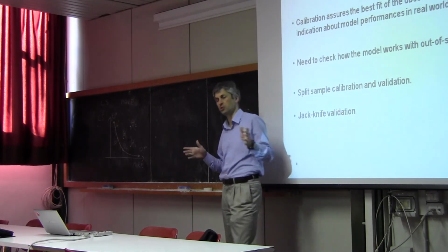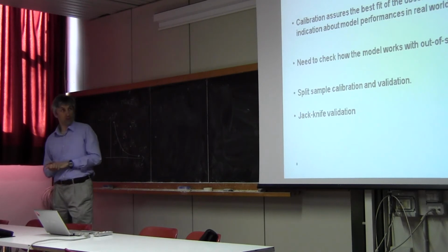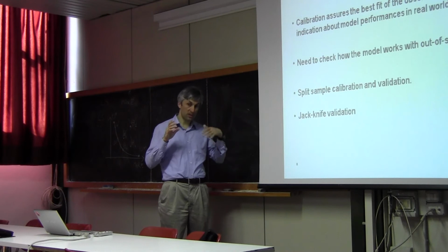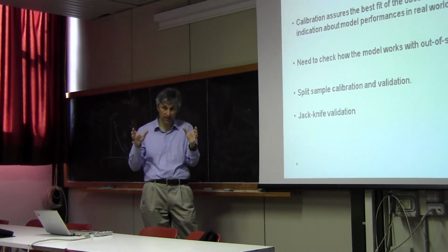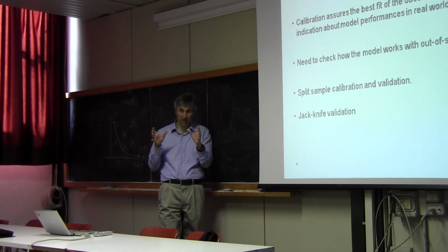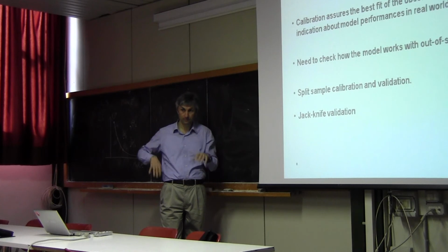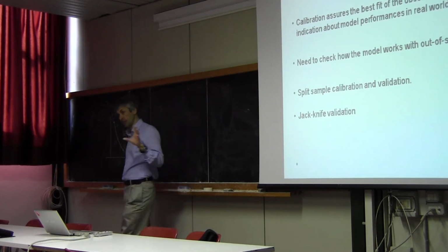If you Google validation and hydrology, you find a lot of entries. So what is validation? Validation is, again, subsequent to calibration. So you already have your model with your parameter vector, and you try to understand how the model performs in a real-world application. It's a check before application.